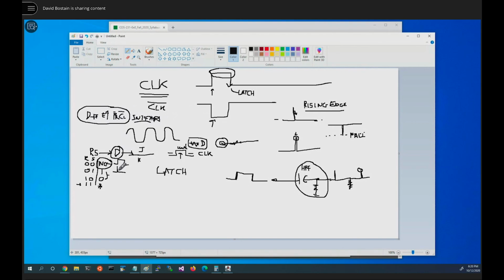Now, they saw in this case the fact that if we uncoupled it, that case didn't have the clock, even though the clock is going to still be useful to a JK. Turns out that we really just did all that tying together to avoid ever having that state. So if we untied them, we can't call them RS because they're no longer RS. They have new names. They have names J and K. We add a fourth state, which instead of no change, set it to 1, set it to 0, the fourth state turns out to be toggle.